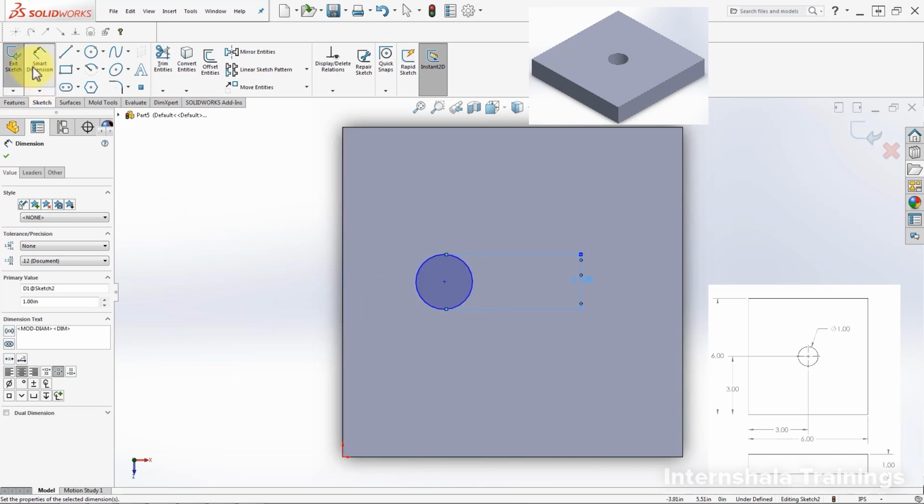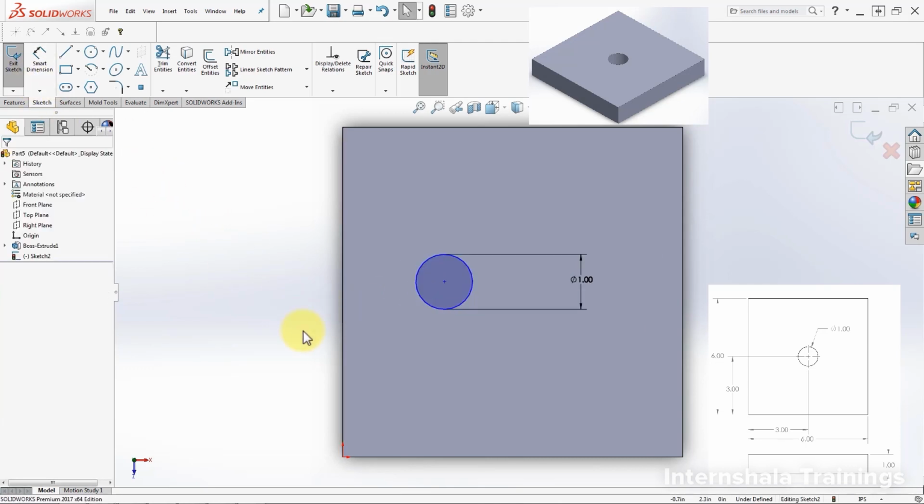Now, what we are going to do differently between the two models is how we define this circle. So please pay attention to this. We're going to do our first approach of defining it. We want the circle to be at the center of the square. Since the square has a side of 6 inches, we can make this to the center by dimensioning the center of it to the side with a dimension of 3 inches. So let's go ahead and do that.